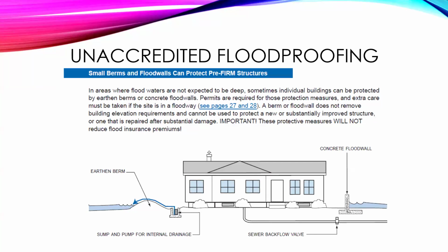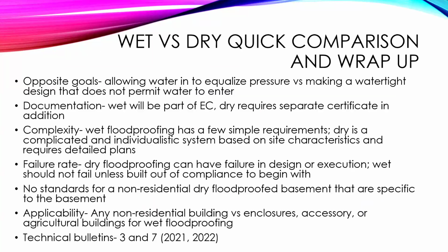So the only type of flood control projects that actually do help with that are certified levees. So those have to be certified and meet the federal requirements for that. And this is something that's commonly misunderstood that I hear from property owners all the time, that this would be the same as that. It's not. This won't actually take you out of the floodplain or remove the mandatory purchase requirement.